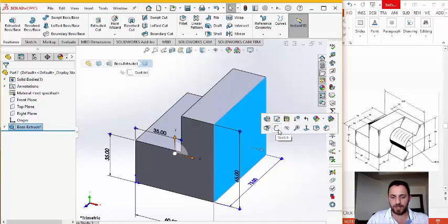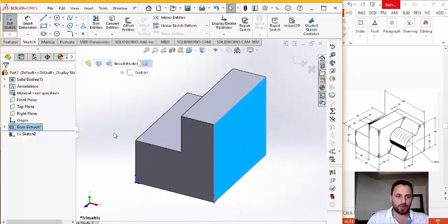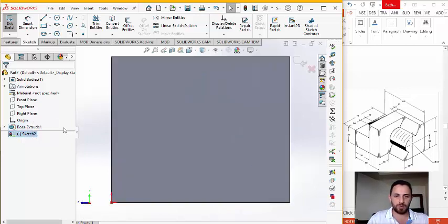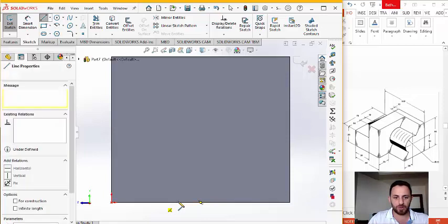Okay, so I sketch on this surface. Either you choose the sketch perpendicular or Ctrl 8 on the keyboard. Okay, I'll start drawing. I choose any point. I advise don't choose like midpoints and others, not to add a relation. So if you choose this point, you add a relation as a fixed point starting from the midpoint. So I choose any point other than the midpoint.